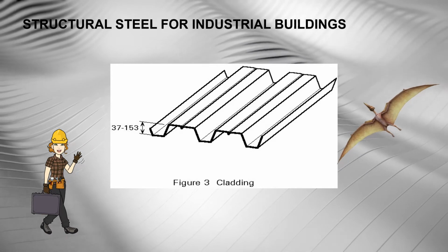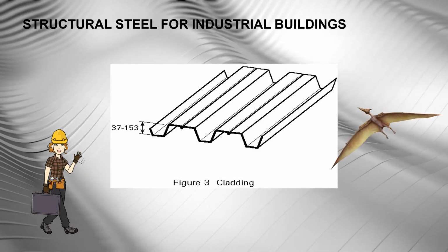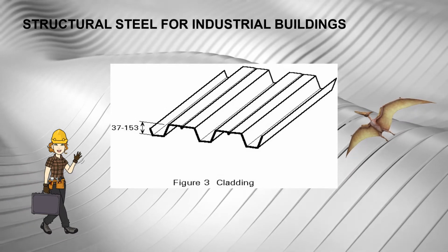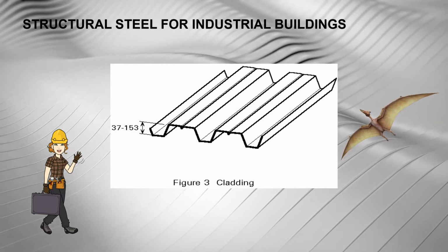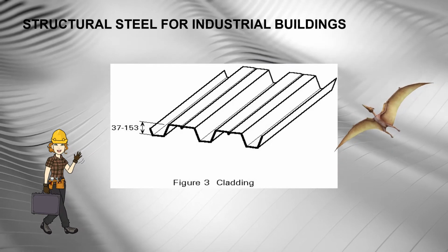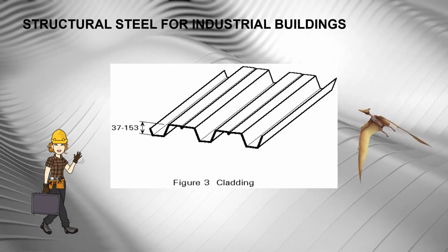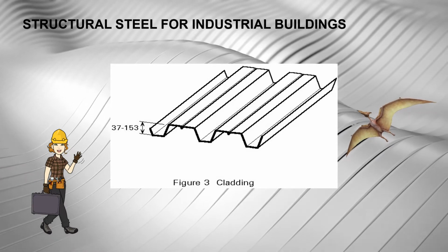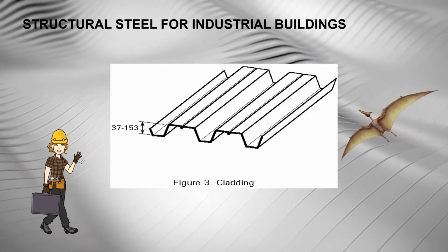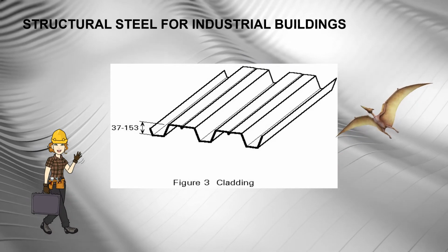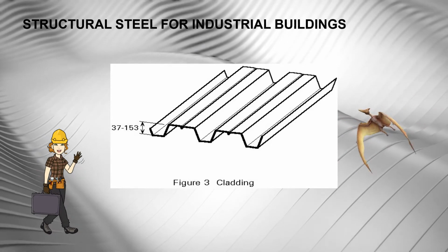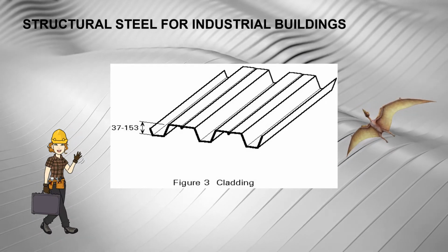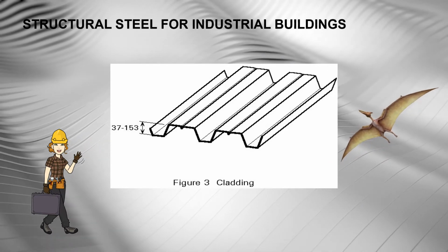The structure of a steel building, especially of an industrial building, is quickly erected and clad, providing a weatherproof envelope which enables the floor and installation of services and internal finishes to proceed at an early stage. Since the construction schedule is always tied to the earliest handover date fixed by production planning, time saved in construction is usually very valuable.